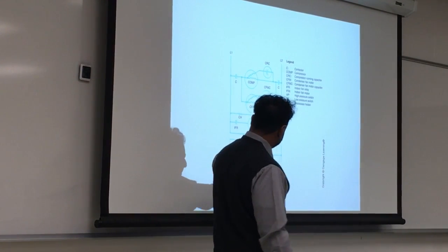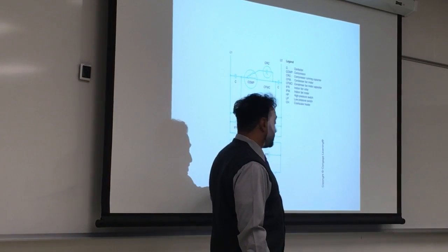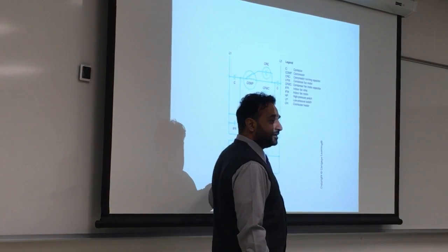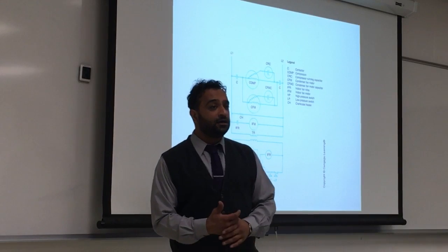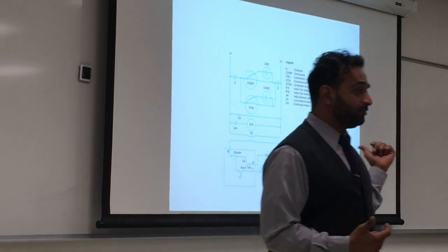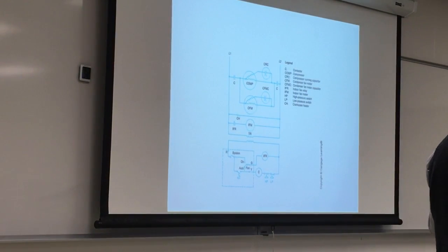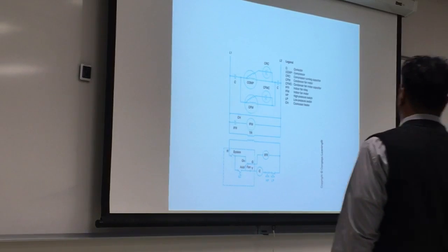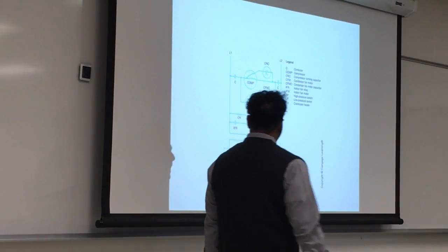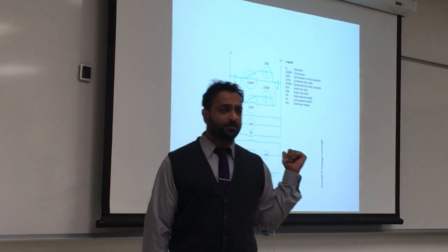They put a dashed line around it to give you some internal wiring, but not a lot. You can just close this and put thermostat. However, when wiring goes through the thermostat board, you will have to connect and understand what R, G, and Y are. If you read any manual, it will probably tell you what the R, G, and Y connect to. This schematic is in the book.